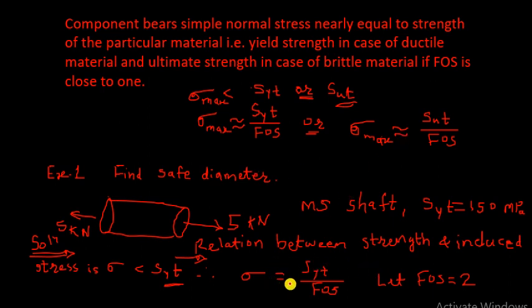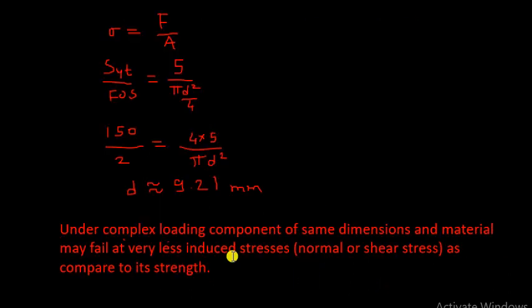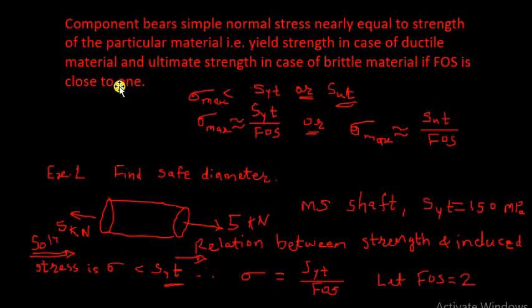Now I will solve this equation and find the diameter. You know that stress is nothing but force upon area, so in the place of stress we will put F by A, and here we will put the values given, that is SYT is given as 150 megapascal.